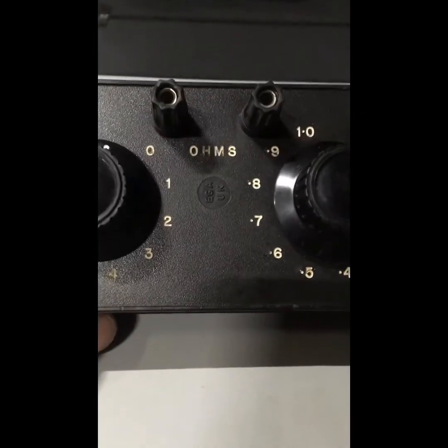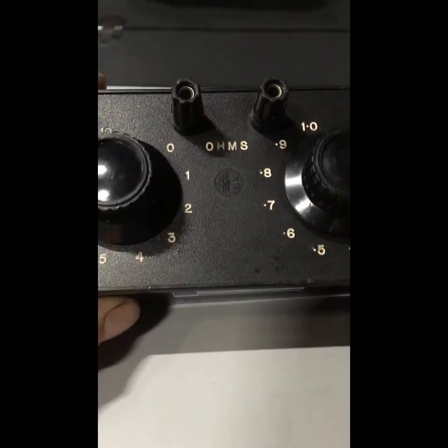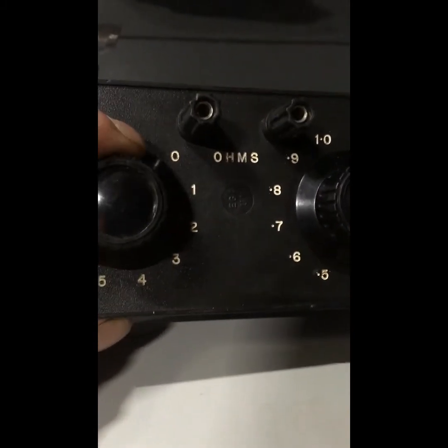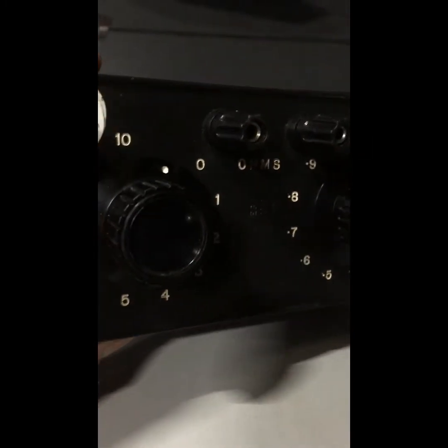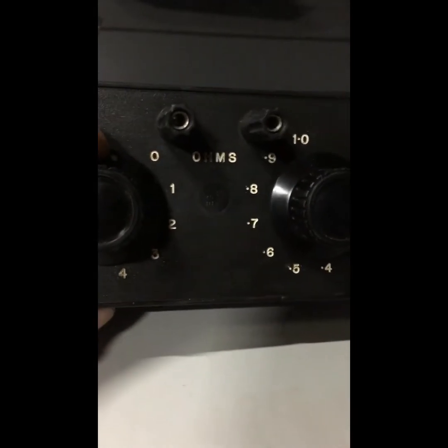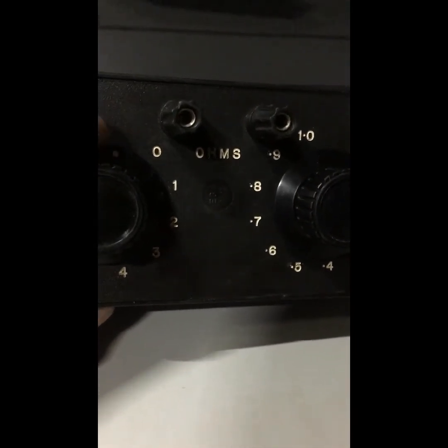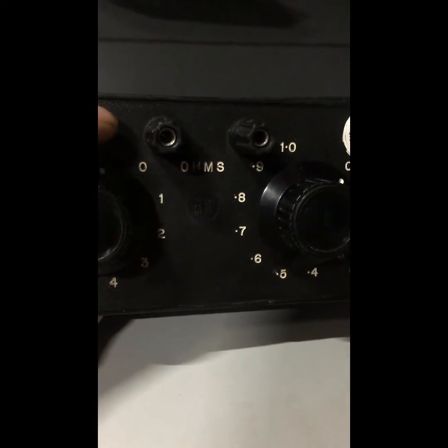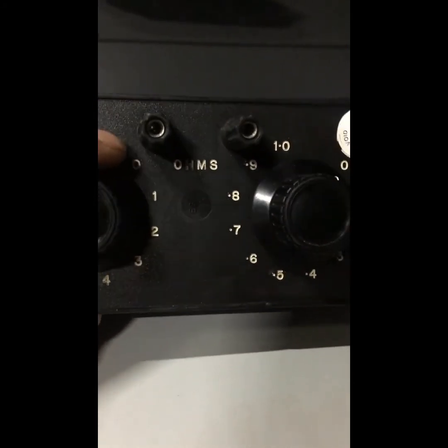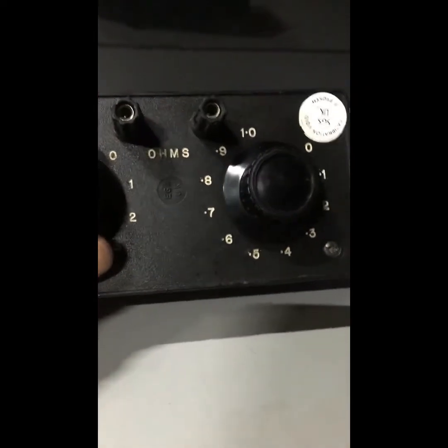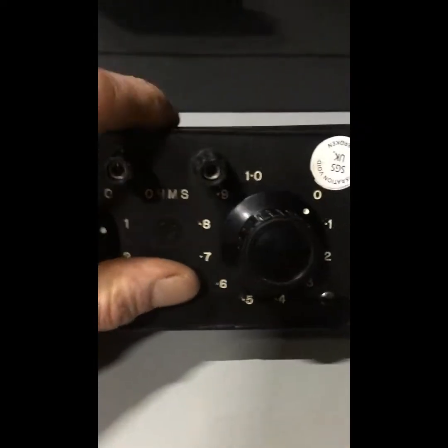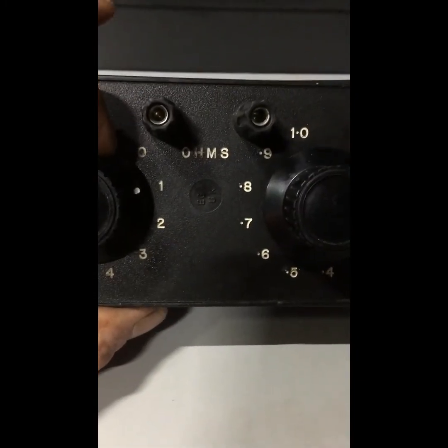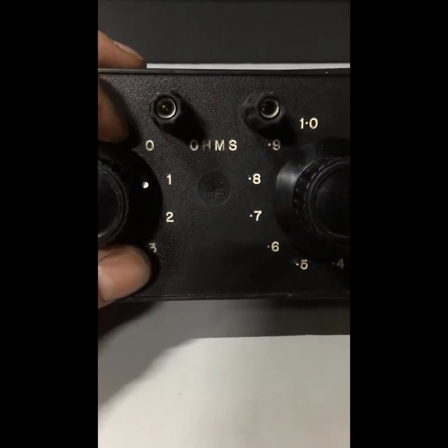The last thing to mention is the testing setup procedure for track circuits. Now, as anyone who's used one of these before would know, this is called a track circuit shunt box, and what we do is we use this for periodic tests and for setting up the track circuit. We're aiming for a resistance value of around 1 ohm, so if I were to set this there, 1, and that side to 0, so that's 1 ohm. That's a nominal shunt value. We aim for around that.